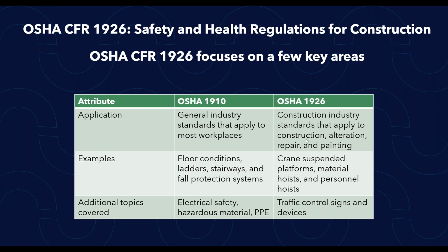Heavy things are moving back and forth, so material handling and hoisting is more of a concern. Also, fall protection is considered differently in 1926, with some different requirements around guardrails, scaffolding, and the 4 foot versus 6 foot requirement, for example, on minimum surface height.